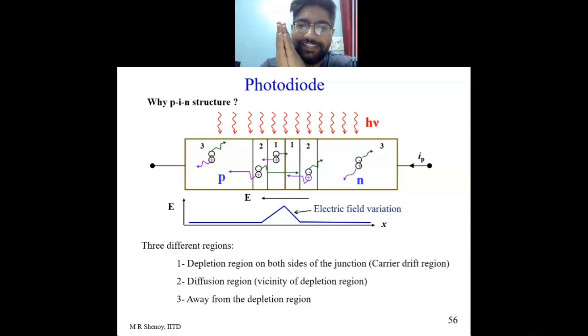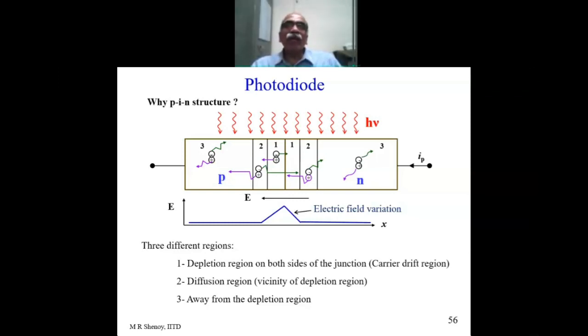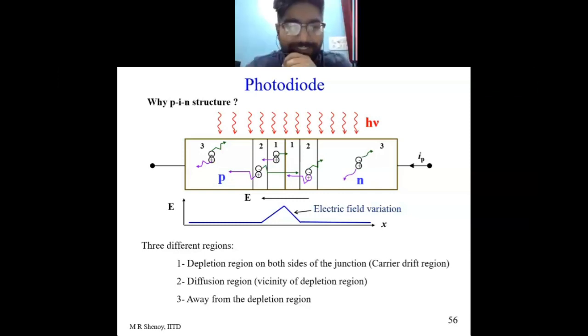So I guess what Arjunan wants to ask is how do we attach the PN junctions? So there are a few techniques. No. PN junctions are not attached. Please remember, when we say it is contact, it is not normal contact. They are called metallurgic contacts. So it's not making contact, because physical contact will not make a PN junction. So you have to really have metallurgic contact, or you have to deposit one material over the other. And then only it will form proper PN contact. Yes, sir. I guess that was what he was asking.